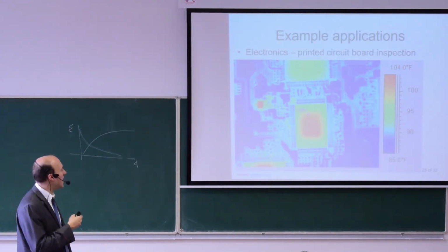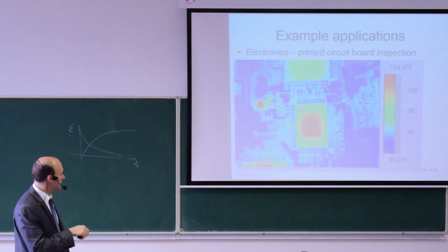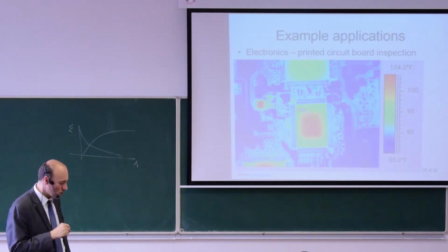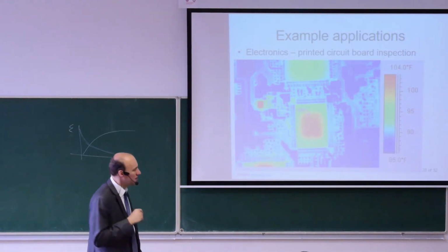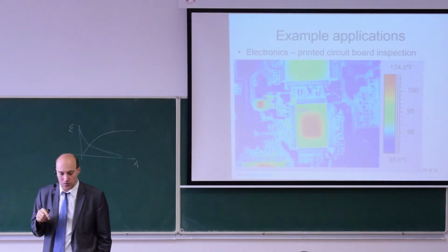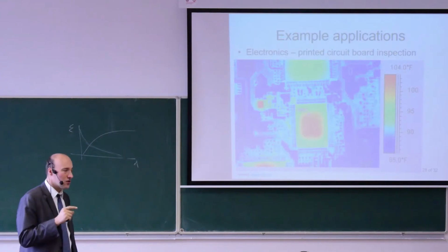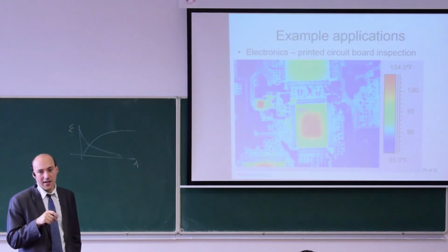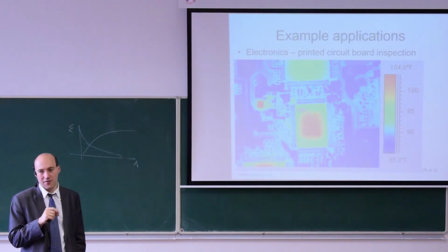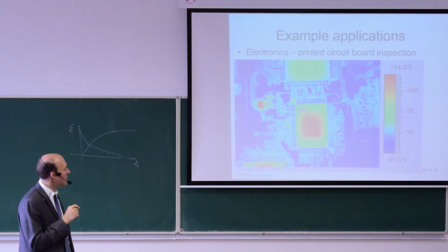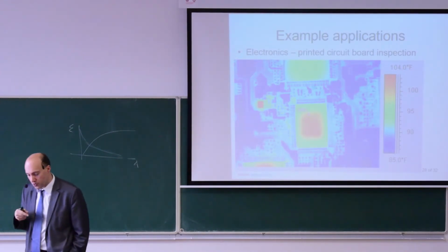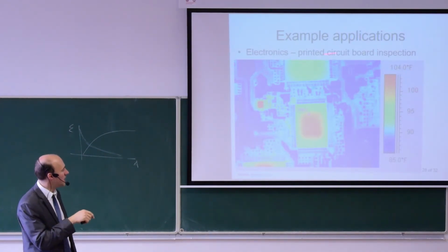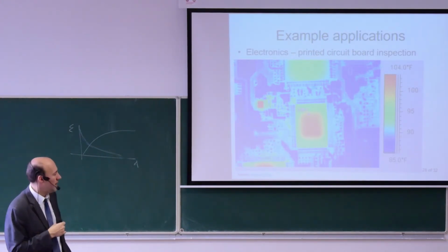So this assumes again that all the surfaces in the image have the same emissivity, which definitely is not true. Fortunately, many materials have emissivity very close to 0.95. So it's not that dependent on color. So for example, if this is green and this is black, it may not have a significantly different emissivity. But it's a function of material, and if you really want to be sure that you read the temperatures, like absolute readings, then you need to paint it with a defined emissivity paint.